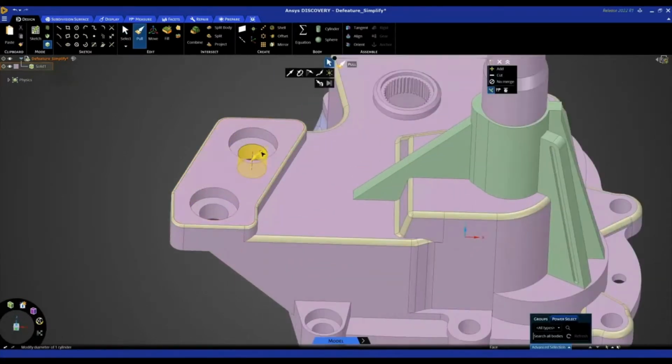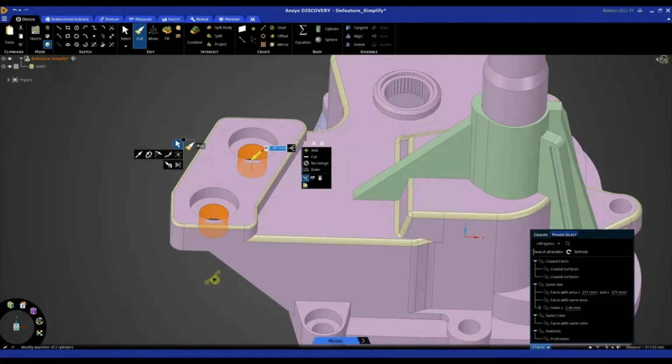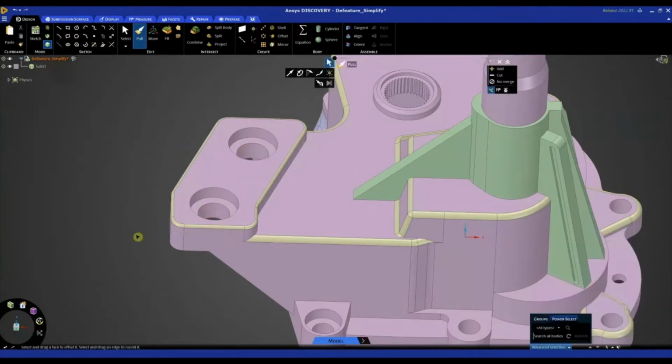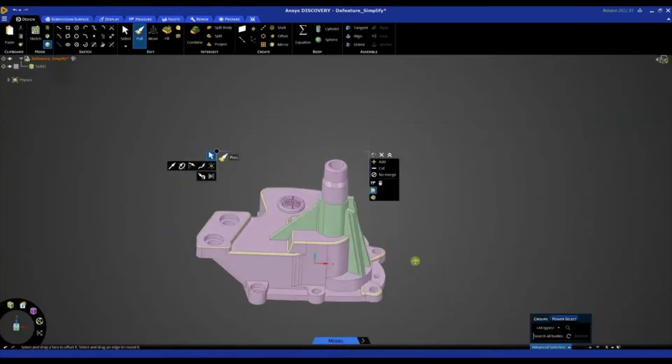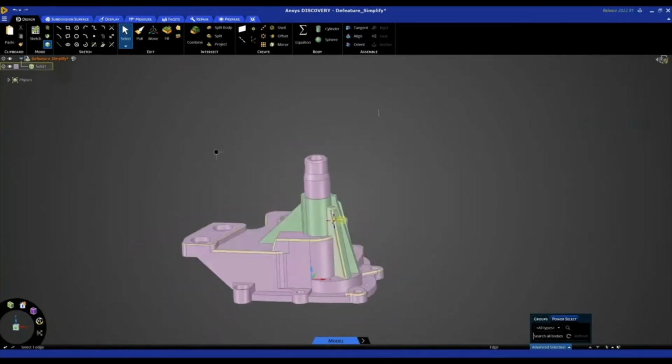Another nice thing is we can use some of our other geometry tools, such as pull. For example, if these holes weren't meant to be 5.461, they're meant to be 6 mil, or you wanted to make a quick geometry change, you can see I've just selected them both, typed in 6, and now the model's updated. So I'm making these live changes on the model, and this is again great for rapid exploration of models when doing simulations.